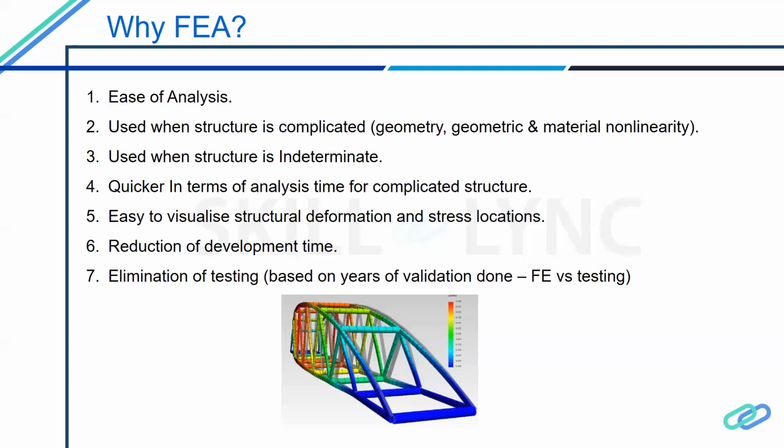Or your FE shows only a little stress in an area, whereas that area has seen high stress and failed in the test. When things like that occur, the customer will normally ask you to first investigate your FE model to see what's going on.